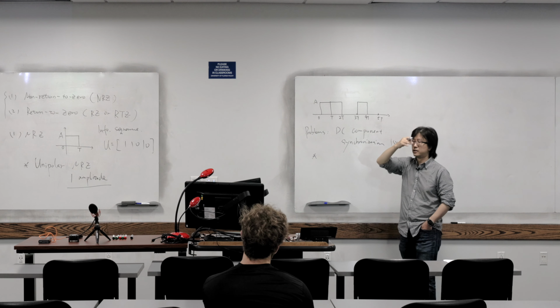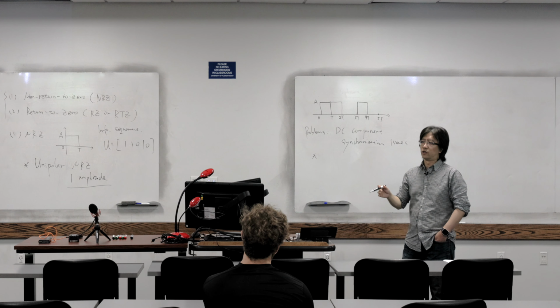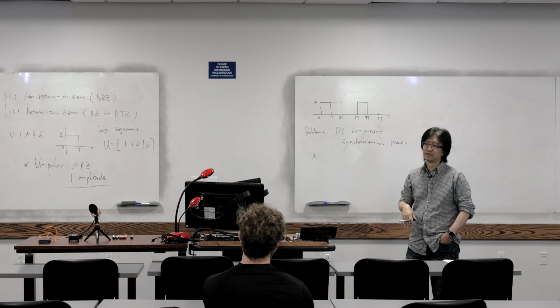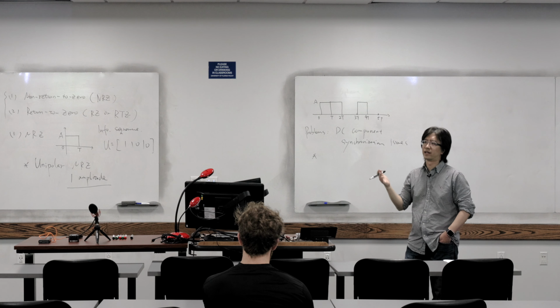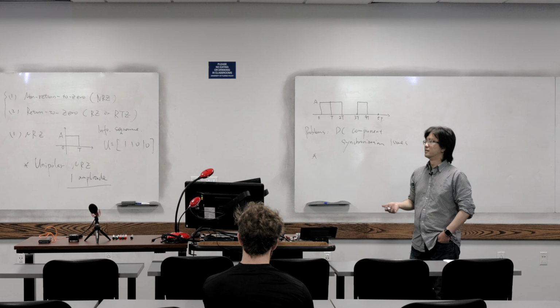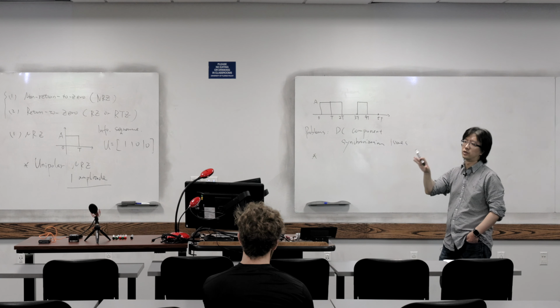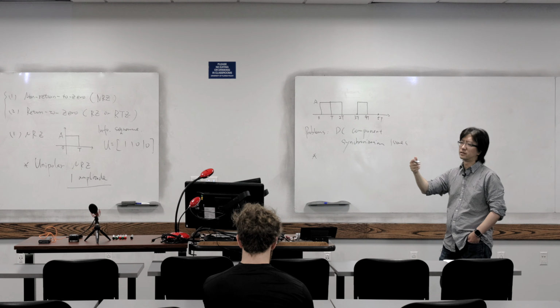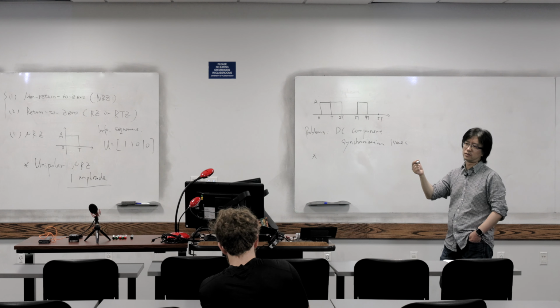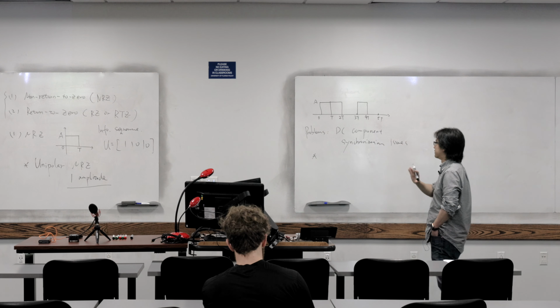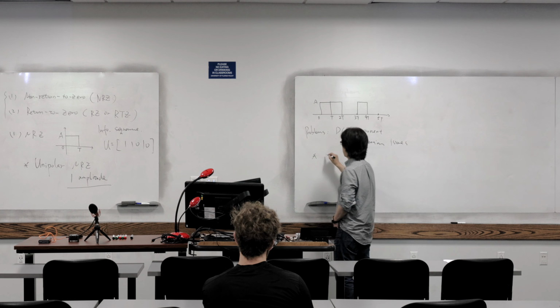Normally, in our transmitted signal, the probability of transmitting 1 and 0 are equal. Why is that? They may not be equal, but if they aren't, we can make them equal. That's called scrambling. But let's assume that normally it's a valid assumption: the source information is equally distributed between 0 and 1, meaning the probability of the signal being 0 is half, and the probability of the signal being 1 is half. So that's a valid assumption. Because of that, we can use so-called bipolar